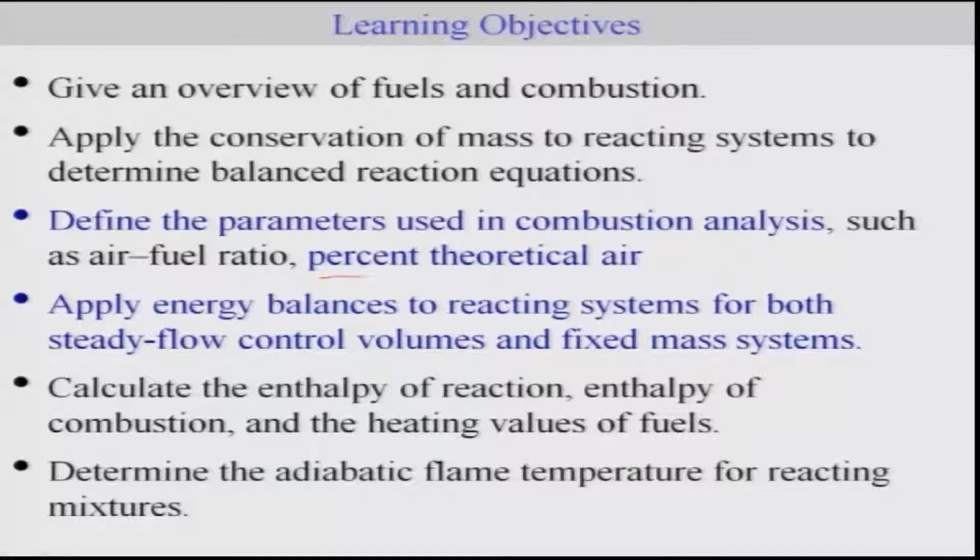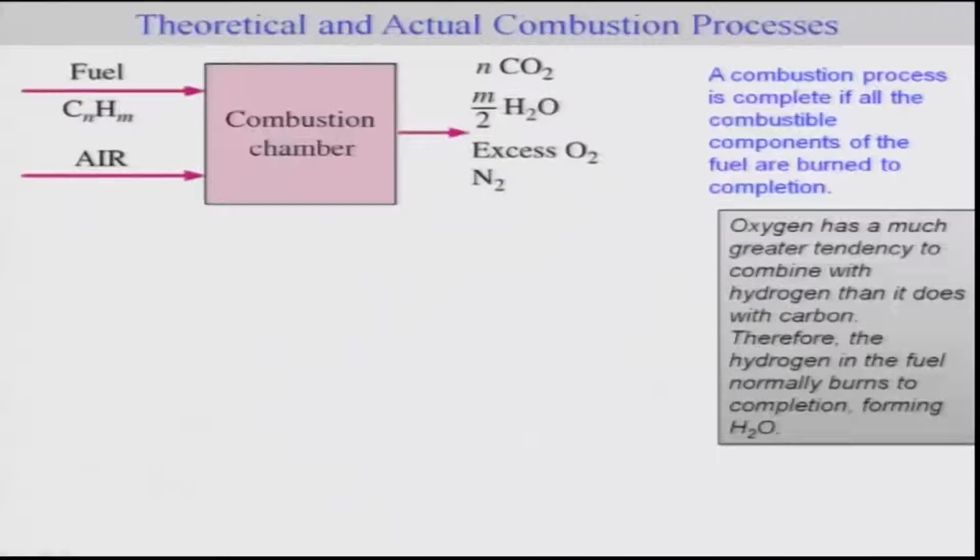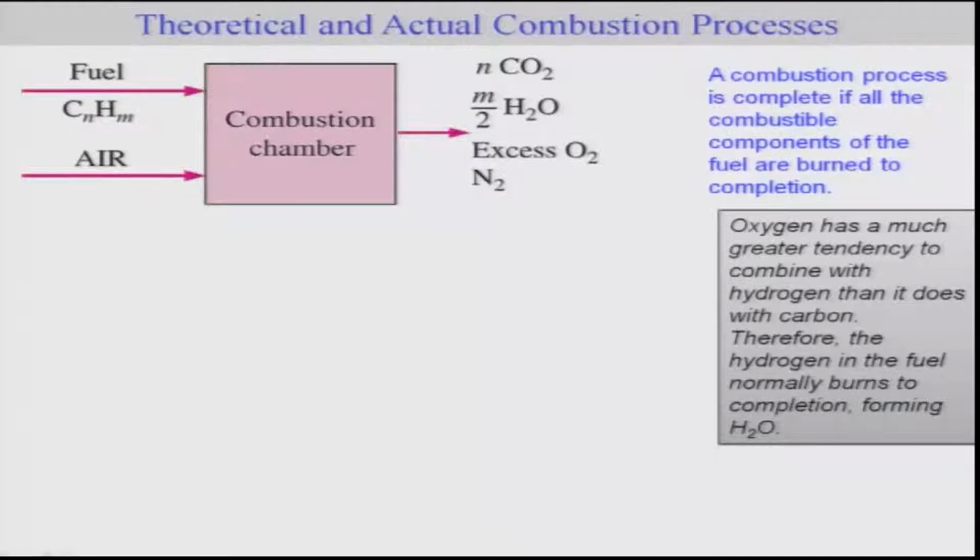particularly the percentage of theoretical air, and we will try to do some energy balance for reacting systems for both steady flow control volume and fixed mass systems. As we realized in our basic analysis, there is a possibility that some of the combustion cannot lead to completion, for example, if the air is not sufficient, or there is a possibility that excess air is given, so the combustion is complete, but you still have some of the air left in the product stream. So a combustion process is complete only if the combustible components of the fuel are burned to completion. So this is kind of a theoretical estimate.